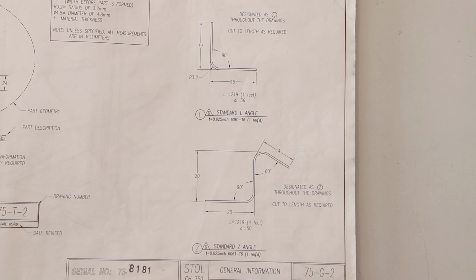Now I'm going to have tons of cutoffs and waste from that, but if you need a 3-foot piece of L and you have to cut a foot off of it, that's just the way it is. To pre-measure, cut, and bend every piece of L in the exact length that it takes to make the plane would take forever. So Zenith used to ship this as a standard 4-foot length because you can cut a 4-foot strip of material off, bend it, and you've got your piece of L. And then if you have a little bit of waste or cut off at the end, then so be it. 64 pieces of L may actually be a lot more material than you need for this airplane.